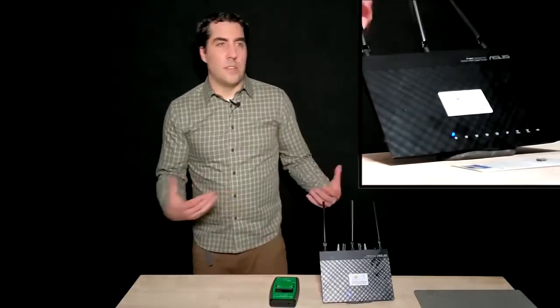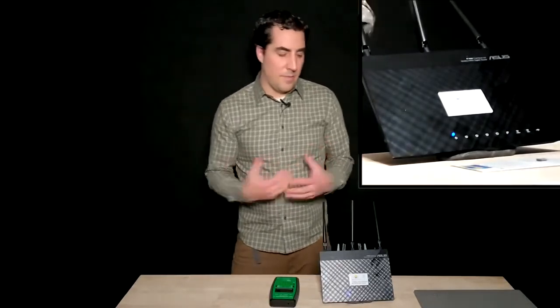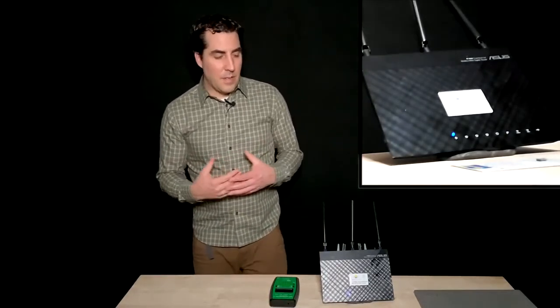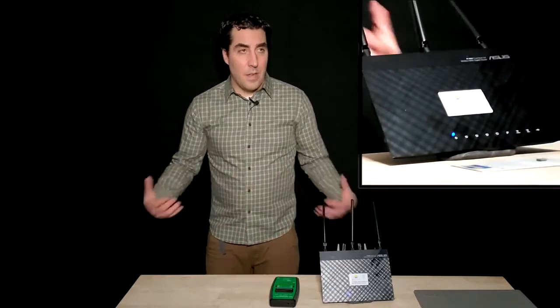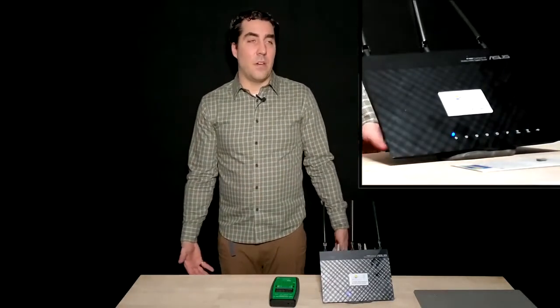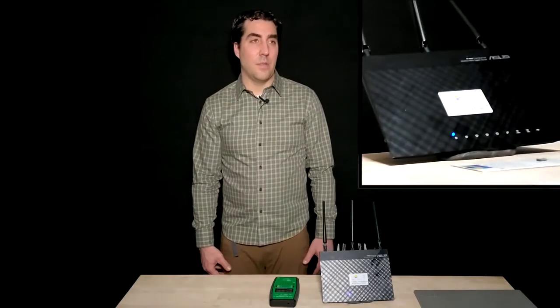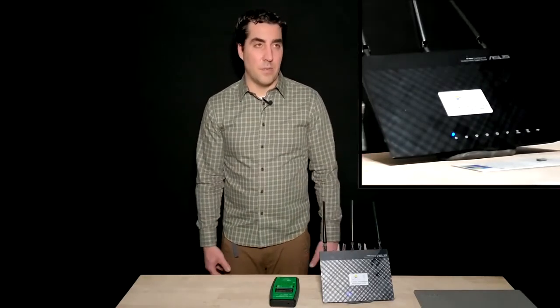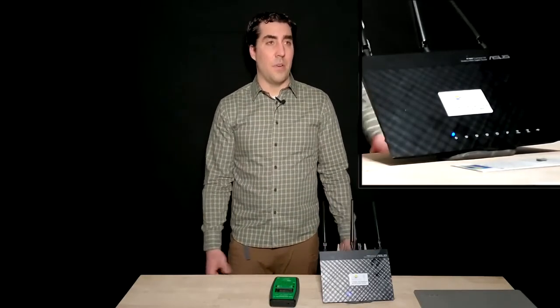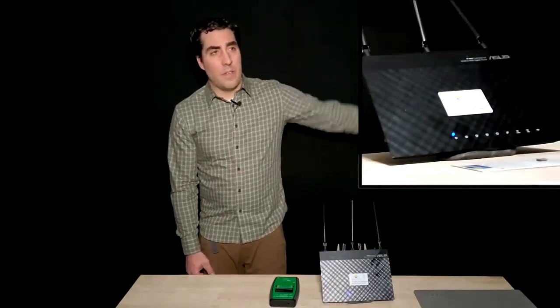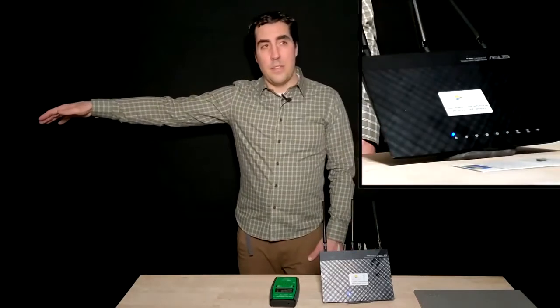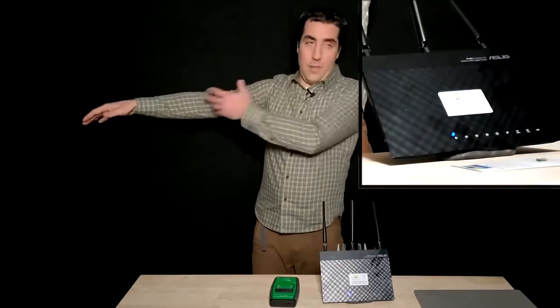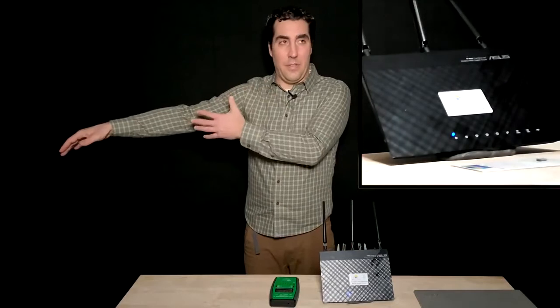This concept of resonant frequency is important, basically because people are conductive and they're going to have a resonant frequency, right? Me standing here, I'm about 6 feet tall, so I'm going to have a resonant frequency of about 100 megahertz, which is around the frequency of FM radio stations. Now, if I put this arm out, it's going to have a different resonant frequency, because it has a different length to it.